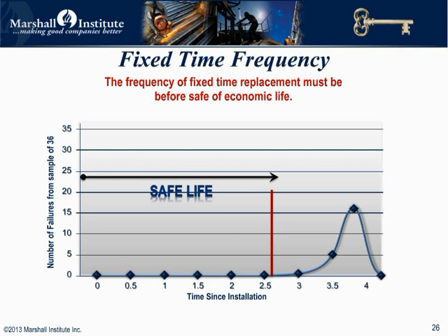We call this the safe life. You pick it based on experience and risk tolerance for the consequences of being wrong. The smaller the consequence, the more risk you're willing to take. The larger the consequence, the less risk you're willing to take, and the more you will reduce the interval until you feel sufficiently safe.